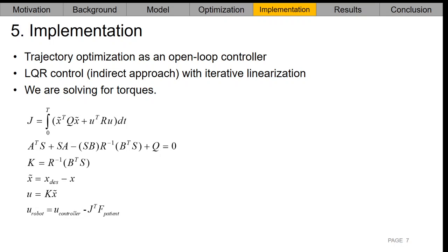First, we can use force sensor data and consider the human-robot interaction model online to calculate the human muscle activations and robot torques at each iteration. Second, we can only consider the robot model online and calculate the patient's contribution by using force sensor data, converting the patient's force to robot torque by using the Jacobian matrix. The robot can then provide the remaining required torque at each iteration.